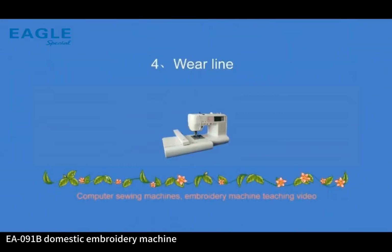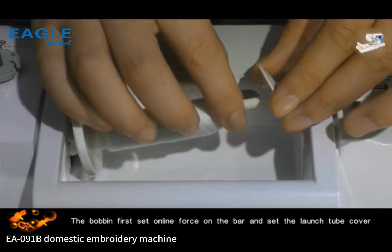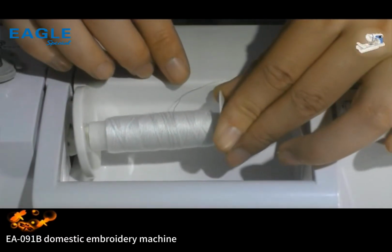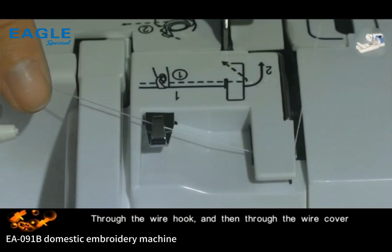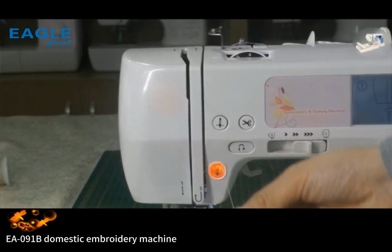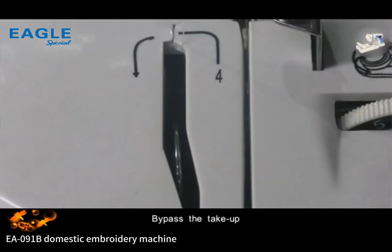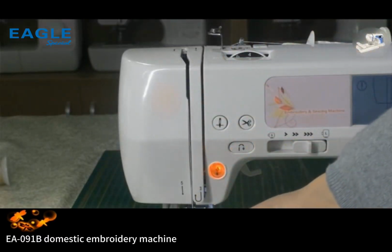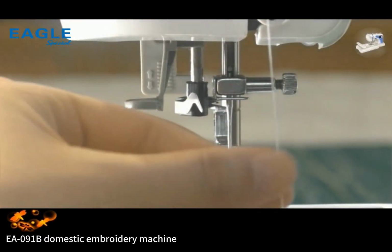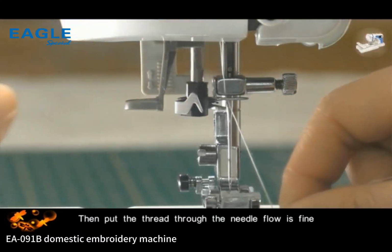4. Threading. Set the thread first on the thread rod and set the cylinder cover. Lead the thread along the path on the icon, through the wire hook, and then through the wire cover. Thread according to the path of the printed icons from 1 to 5. Bypass the take-up. Then put the thread through the needle and it is fine.